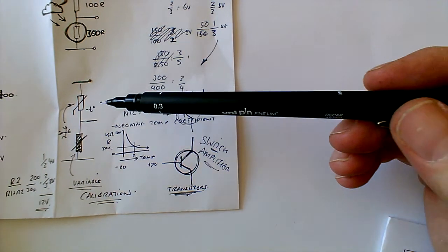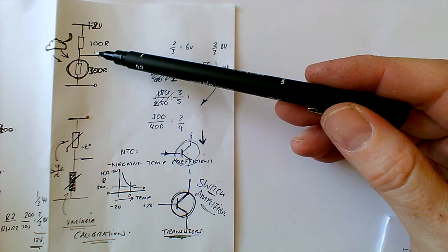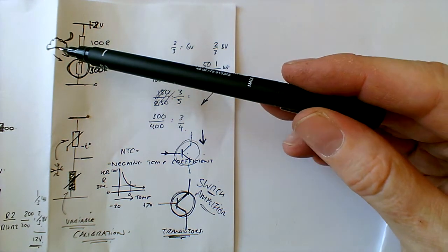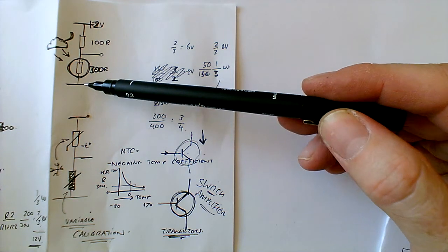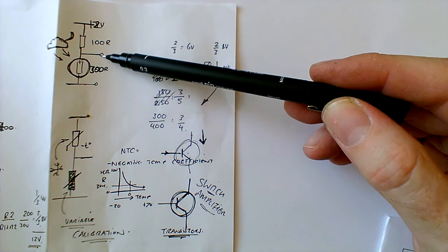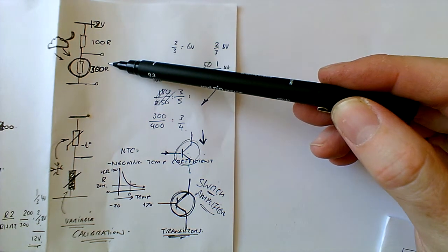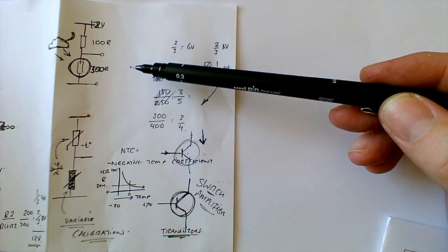we'd used a potential divider as a sensor. Here we've got two. We've got a light sensor here, the light dependent resistor, where the darkness or the cloud obscures the light, increases the resistance, and therefore increases the voltage across these 2 points, so that the voltage here was increased, triggering some response.